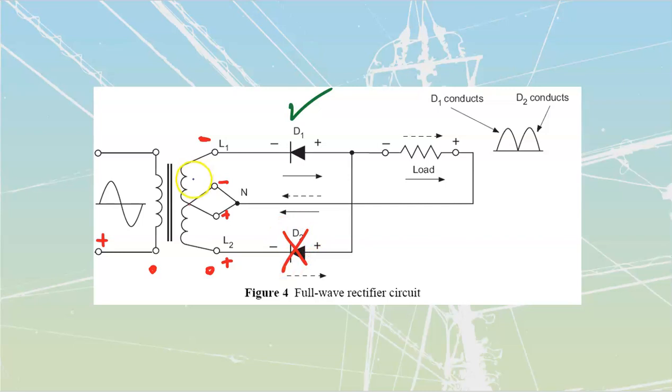And if I take a look, I do have voltage that is going to be impressed across these secondaries, right? Just because there's no current flowing doesn't mean that there's necessarily going to be no voltage. But if I were to take a look at it, I could see that I'm taking this negative here. We're going to flow current through there out to that point. So we're going to pass that negative through to there. As far as voltage goes, I can see I'm putting that negative all the way through to here. And then if I follow the rest of this path through here, I see that I'm going to be placing that positive all the way over here. In other words, that diode is blocking that complete path that we are going to have over there.